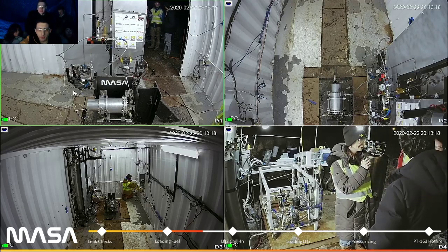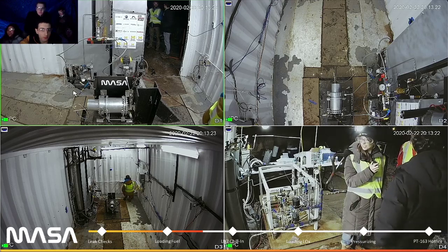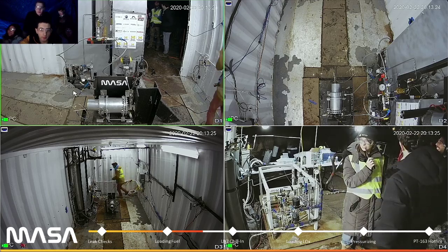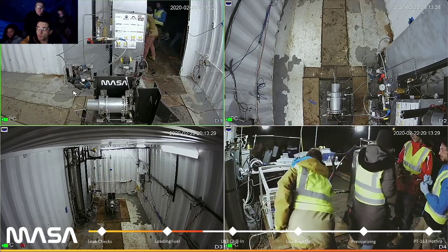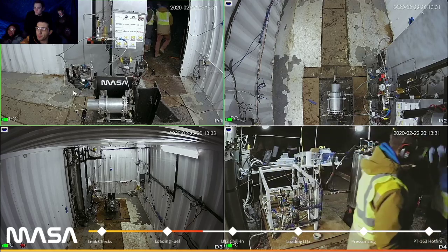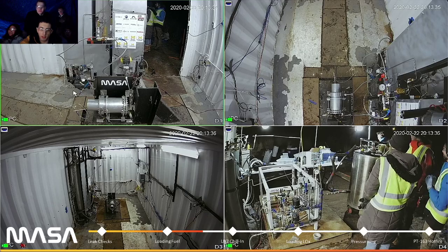You say that's not horrible. Well, one 50 thou hole drilled perpendicular to your piece might not be horrible, but if you drill hundreds of holes at various angles and you can't mess up a single one of them, or else you have to scrap your injector, that's pretty difficult. So that's why we have that done out of house.